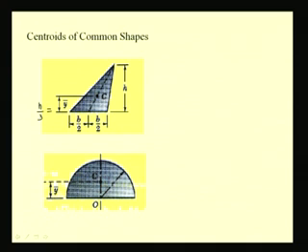If r is the radius, and if we integrate it, we can find this quantity y bar as 4r by 3 pi. So, for common shapes, these values, that is the centroids x bar and y bar, are tabulated and they are available for use for various computations.